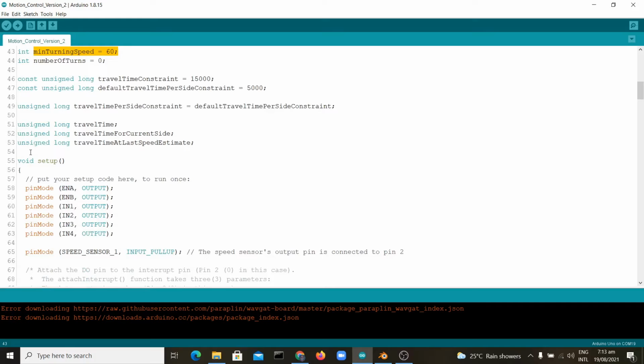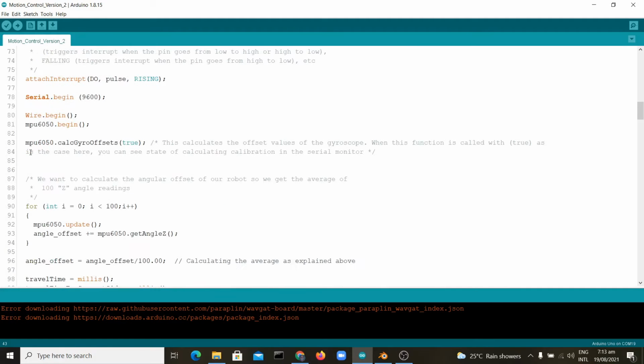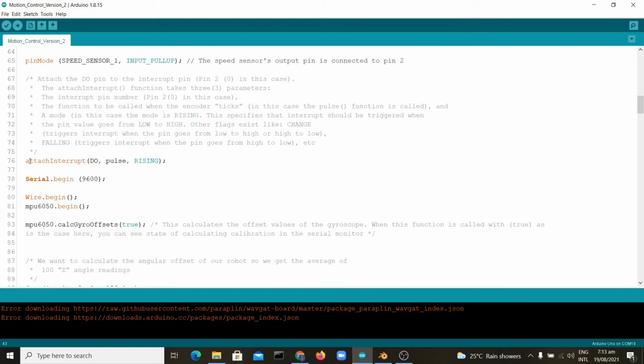Everything else is straightforward. Over here, when I attach the interrupt, I use the value RISING. I only wanted to raise an interrupt when the output pin, the T0 pin of the speed sensor, goes from low to high. I think that is when the disk moves from a hole to not a hole or something. Anyhow, the proper value is either RISING or FALLING, but not CHANGE.